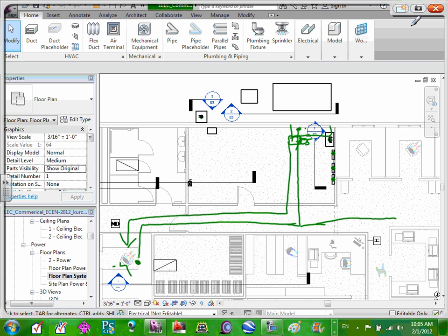A tamper switch, there is, we asked for 2 of them. There's gate valves. Picture just a big wheel on the sides of your fire protection assembly. There's gate valves that you can completely shut off your system. Your fire protection system is shut off. The water will not flow to any of the sprinkler heads if you close this gate valve.